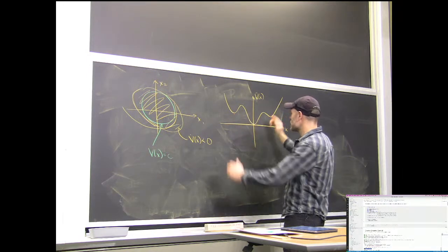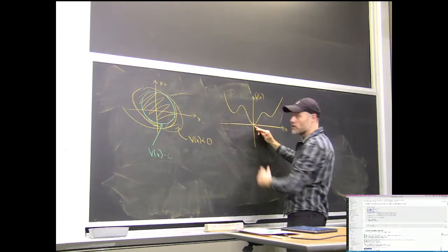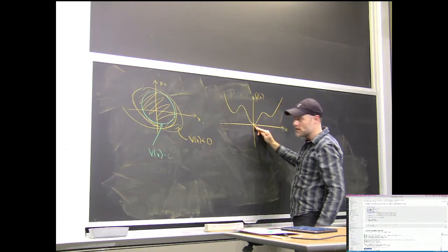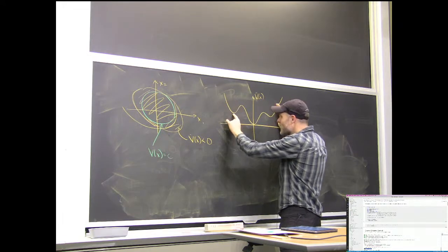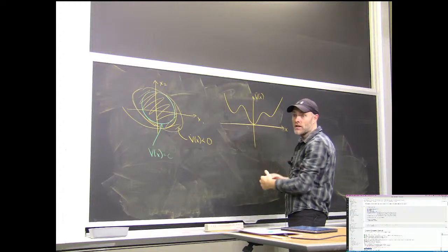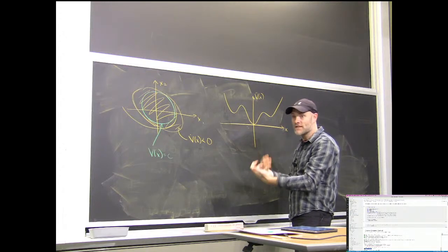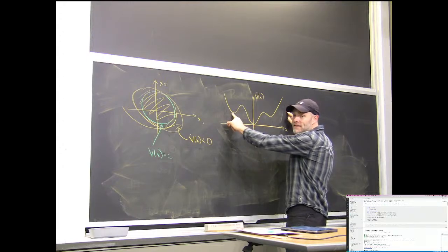So you can't have an asymptotic stability region of attraction that goes to the origin. In the case of less than or equal to 0, you can satisfy that here, but that's okay. That's why stability in the sense of Lyapunov is different. It doesn't say you get to the origin. It just says you don't leave too far.